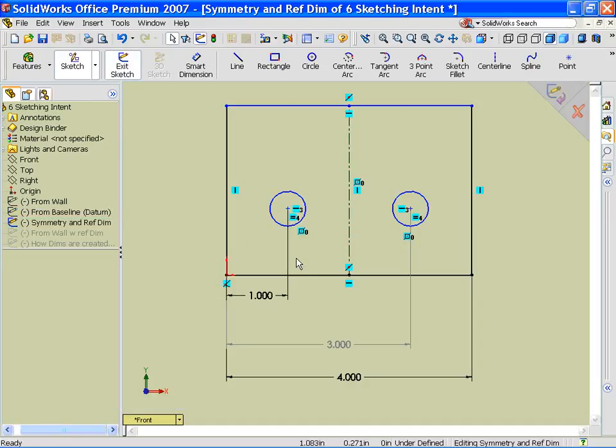we can still say, okay, SOLIDWORKS, I want this to be centered about my part, which I did a standard mirror here. I did my dimension on the 1 and then added a reference dimension. And the reason this is all important, what I'm talking about, is when you get to the drawing, ultimately you want to be importing your model items, thereby not redimensioning the model but literally pulling in these dimensions.